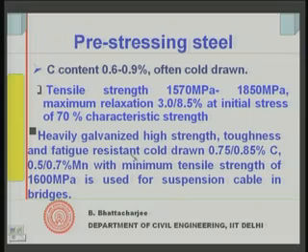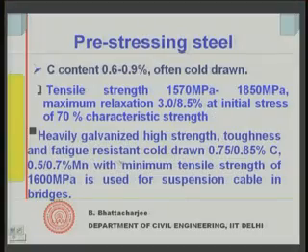Suspension bridge cables have to withstand a lot of horizontal movement of the deck. So, they have to withstand stresses related to this swing of the deck, and so on. Therefore, they must have a lot of toughness or impact resistance, and good fatigue resistance, because reversal of stresses would be there, not only because of the load on the road or the deck, but also because of the wind forces. So, we need high strength, toughness and fatigue resistance.